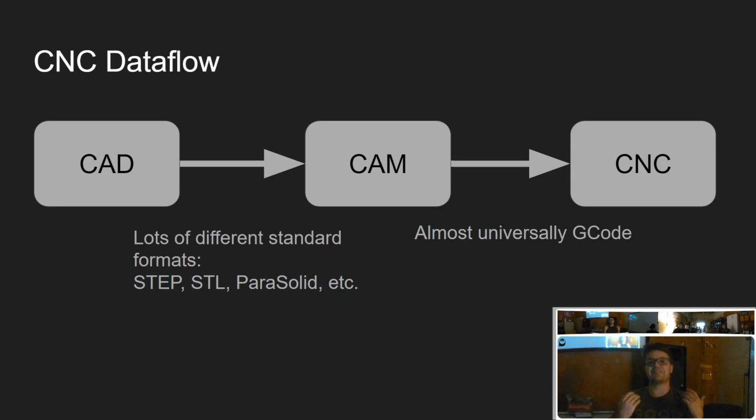What you'll find is there's this hell of post-processors, where in whatever CAM software you're using, when you're done laying out the operations that you want to do, you're going to click export, and you're going to pick, I'm exporting to a Haas, or I'm exporting to LinuxCNC, or I'm exporting to a Tormach, and it'll add different flavors of G-code instructions to that for the different machines to understand.